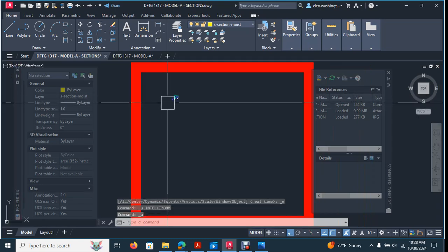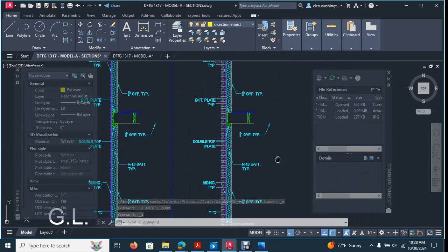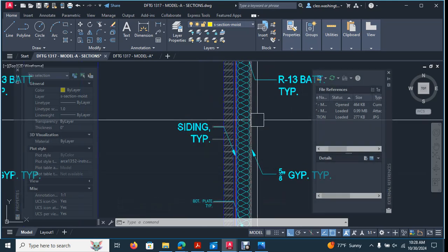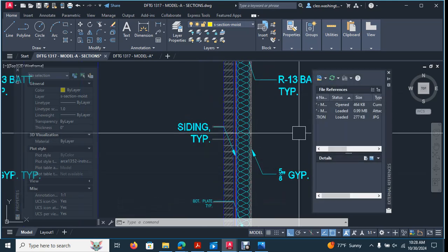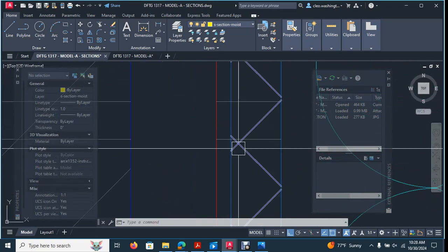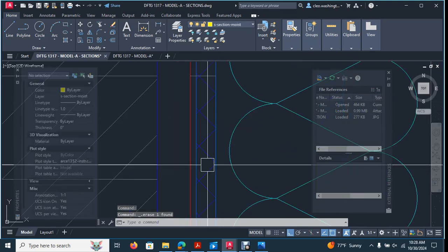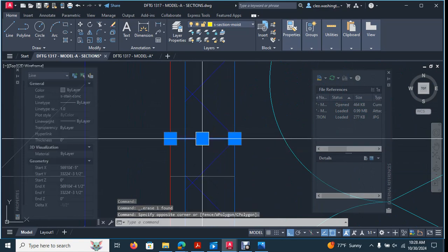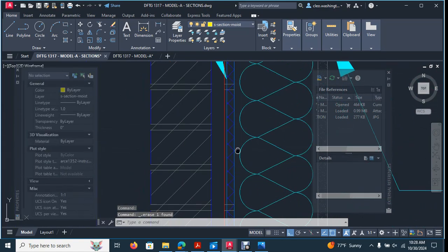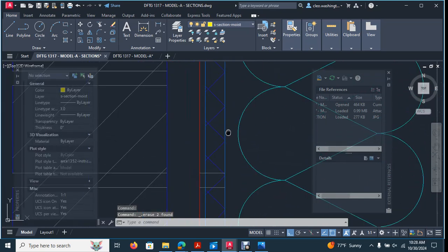And you will have that happen. If you double click your mouse wheel, you will zoom all the way out. A lot of times you can just undo till you get the zoom view that you want, or you can type in ZE and hit the space bar for zoom extents, and that'll center you back up on your drawing. So let's go ahead and just take all of these guys out again. Another tedious bit of work, but it's just part of the process.